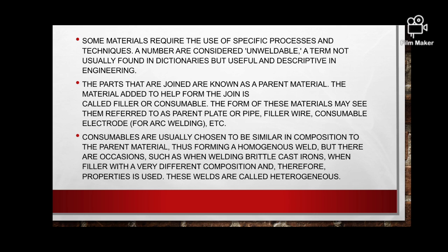Consumables are usually chosen to be similar in composition to the parent material, thus forming a homogeneous weld. But there are occasions, such as when welding brittle cast iron, when filler with a very different composition, and therefore properties, is used. These welds are called heterogeneous.